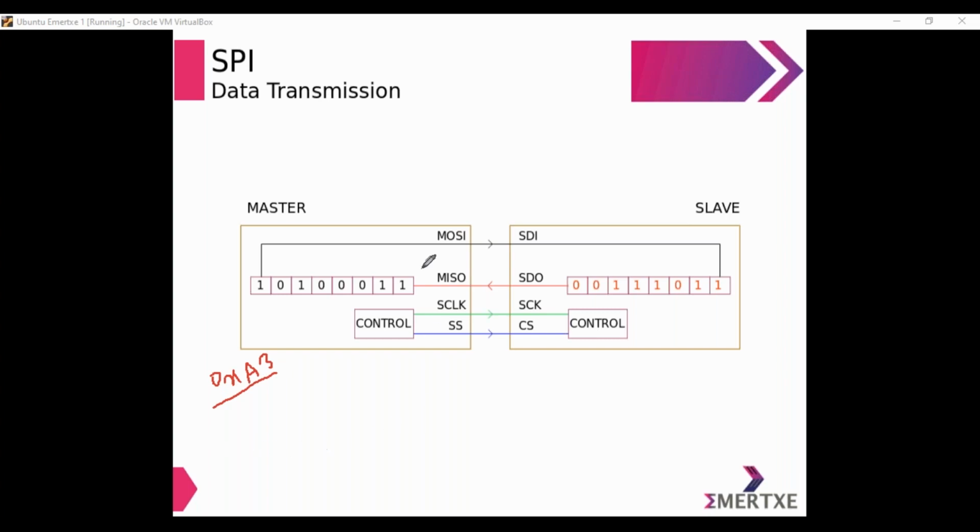From the buffer register, it gets returned to the shift register. From the shift register, data gets shifted bit by bit. Now after I perform the shift operation once, you can see whatever is in the MSB will go to the LSB of the slave. See? Whatever I had in the MSB came to the LSB of the slave.